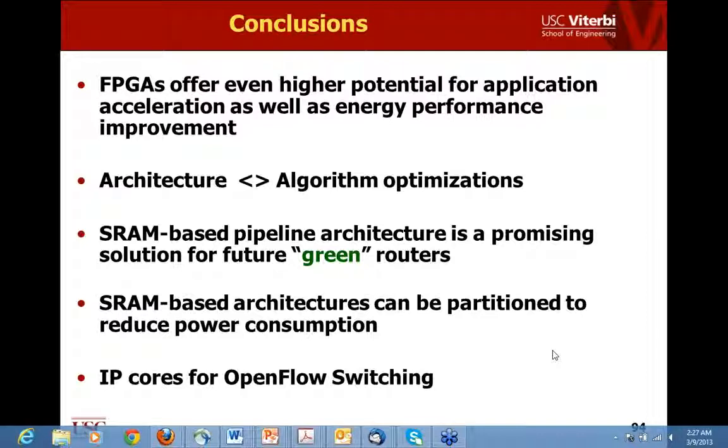We have, in front of those pipelines, a small piece of hardware, the index table hardware, which could be a small CAM, which essentially makes a table lookup and decides which one of those pipelines is to be used. So the decision making is done in that initial stage, which tells which way the packet header is to be routed.